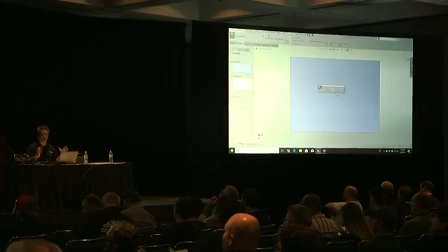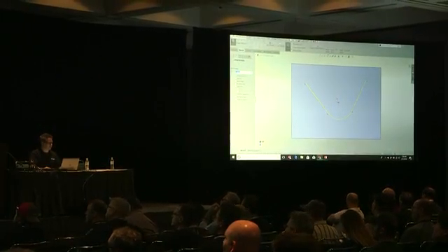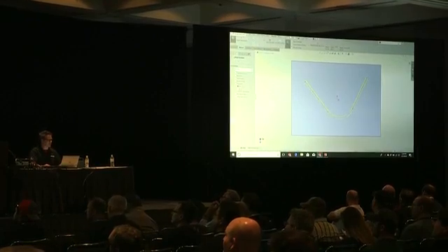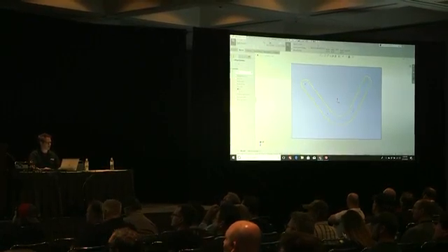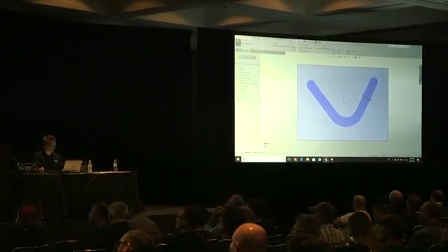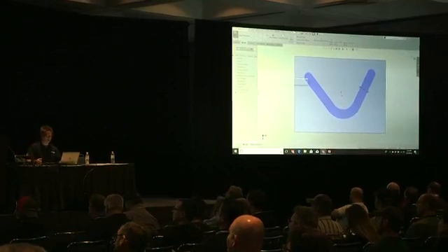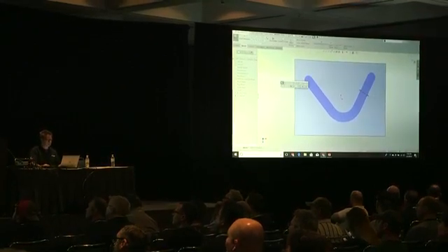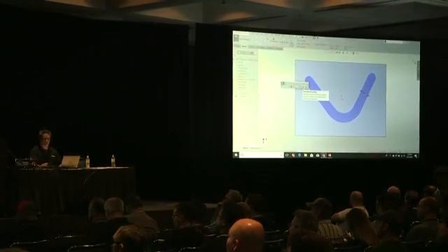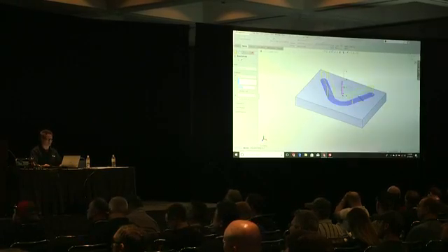You know, just bear with me. So I'm going to do offset. I'm going to jump over here, cap the ends, bidirectional, make it a little bit more noticeable. Say OK. Now, because I use the S key so much, when I'm in a sketch, how do you get out of a sketch? You extrude or you cut. Put those on your shortcut. It's customizable. Just right-click on it, customize it. Real basic stuff. Nothing crazy fancy yet.